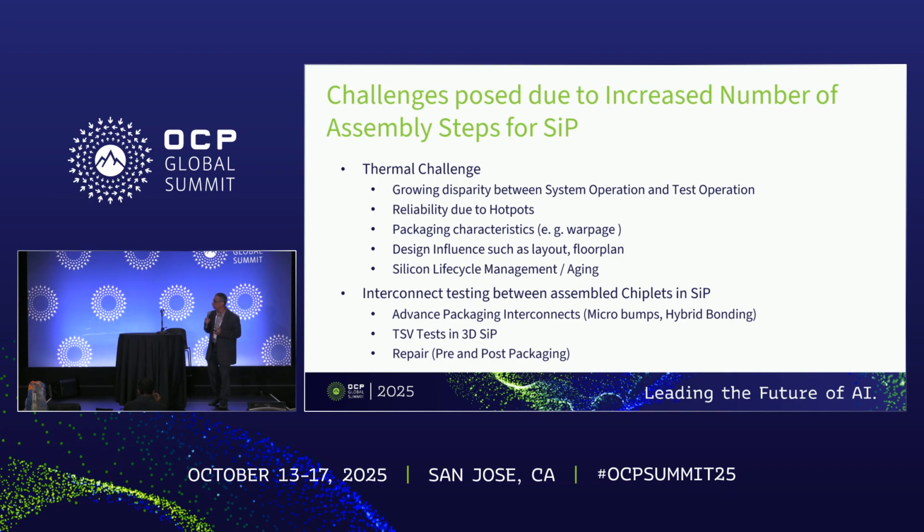And second, very important, is interconnect. We are building three-dimensional stacks now using TSVs. And especially now microbumps have gone to hybrid bonding, which is, I think, at the order of 2 micrometer pitch. And you can imagine how complex that process is, that if there is a particle, it is going to affect more balls compared to microbumps. That kind of defect is going to make the entire cluster useless. So we have to have spare structures. That is called repair.